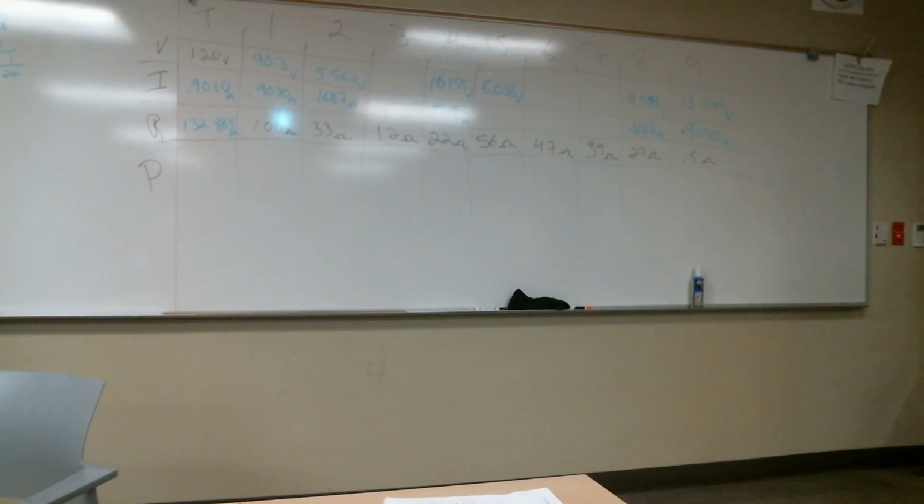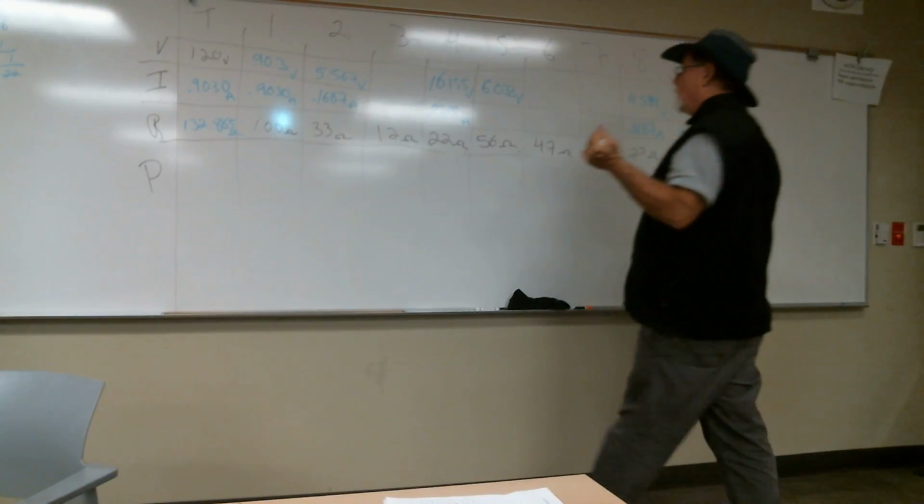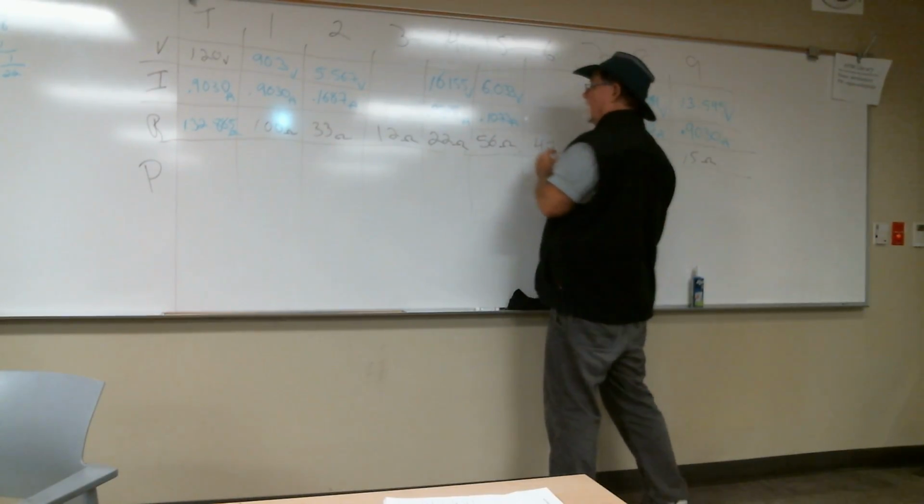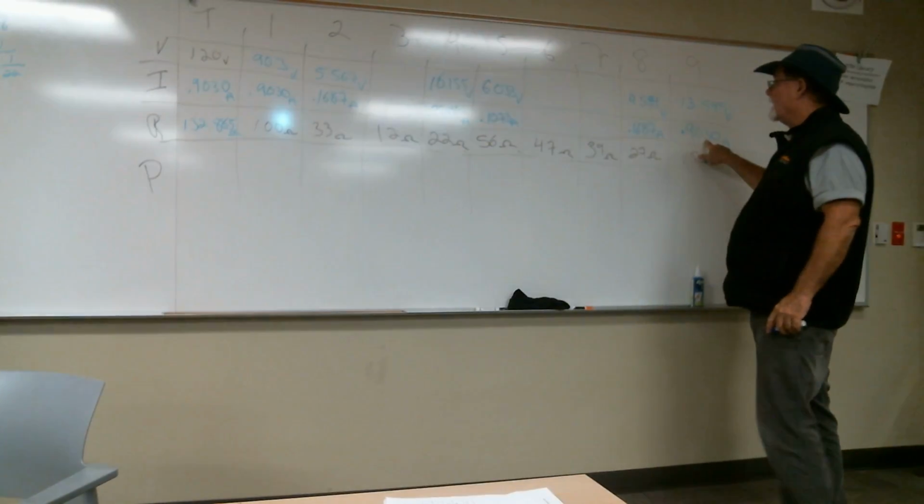Voltage drop. Now the only thing left that I can calculate at this point is the current going through the branch of R5, and it's really the remainder of what came through 2 and 8. So 6 divided by 56 is going to be a really small number. I'm not even going to try and do that in my head. The amperage for R5 is 0.1073. Correct. Okay. Well, that's definitely less than total amperage.